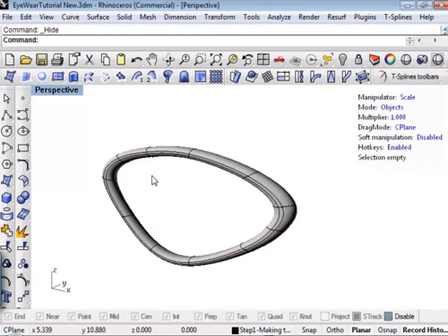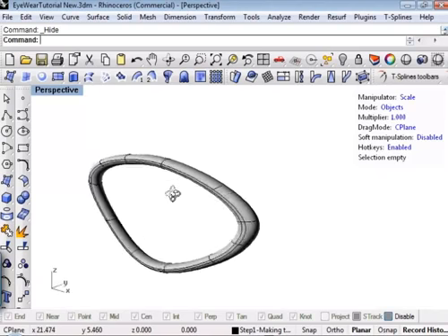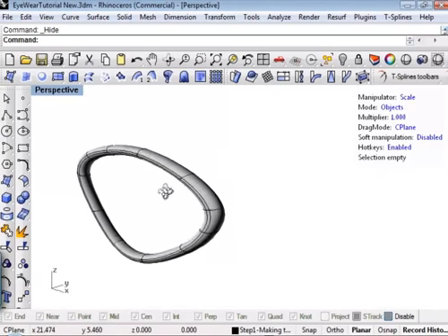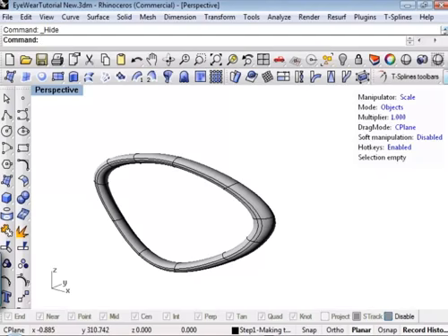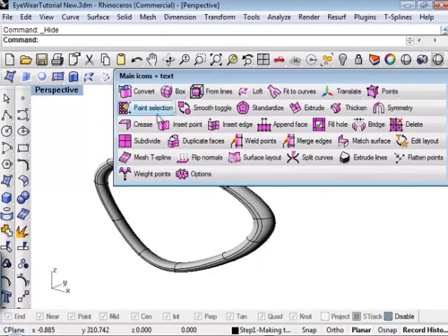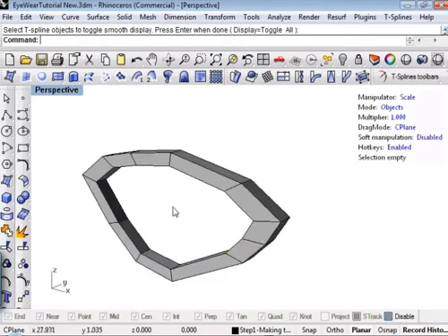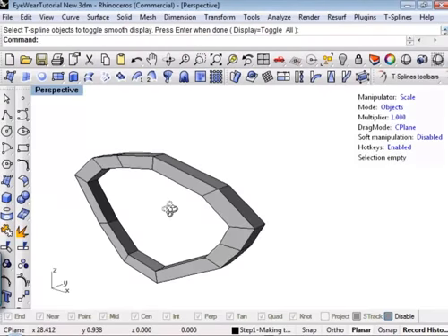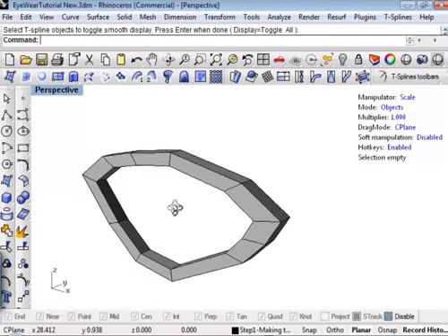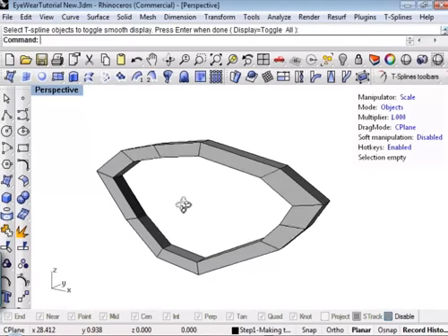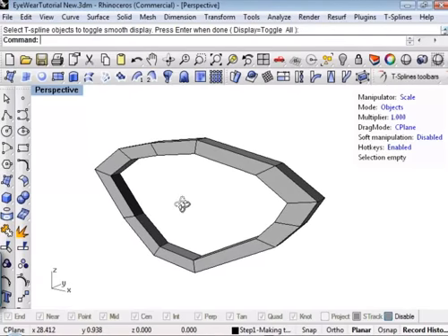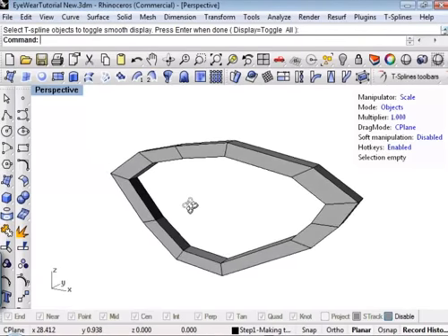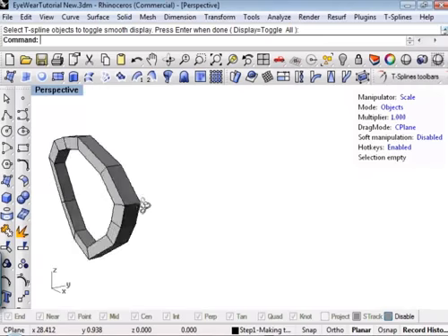There's two modes in T Splines, and those of you who downloaded this and started using it may notice that there's a smooth mode, which is the visual representation of what the interpolated surface looks like. And then there's box mode, which if I hit the smooth toggle button up here, you'll notice that it shows the polygonal representation of what the model actually is.